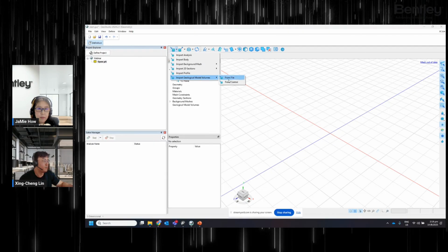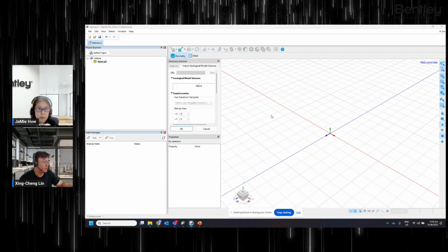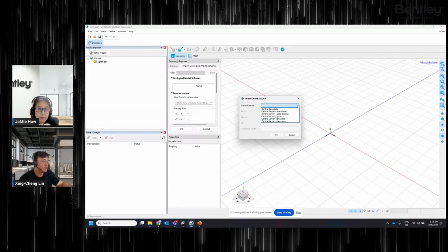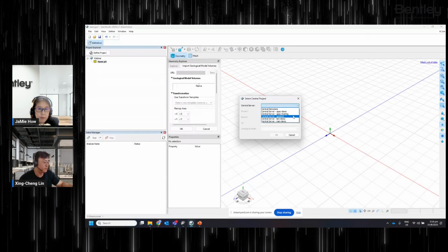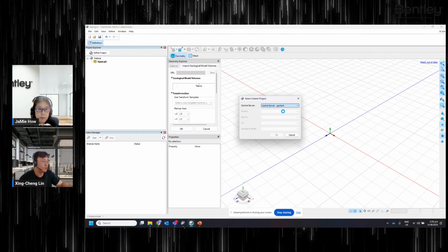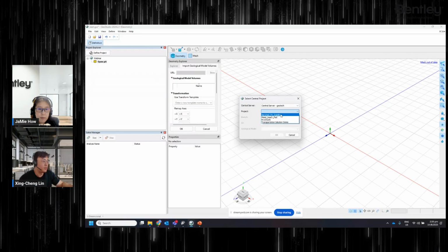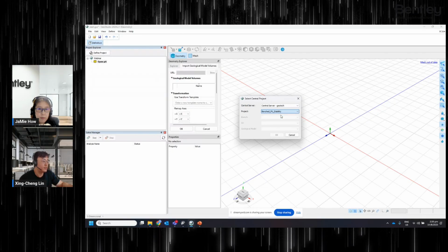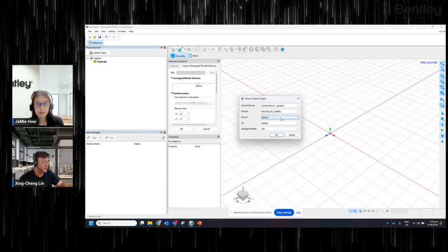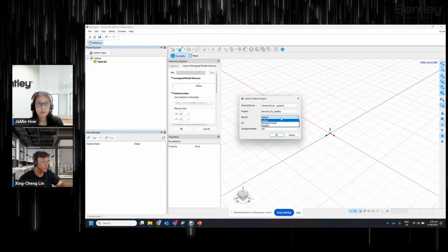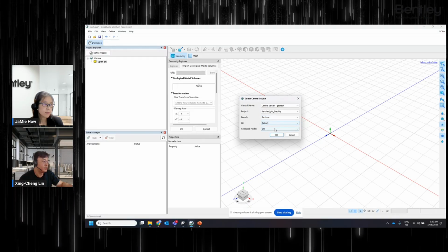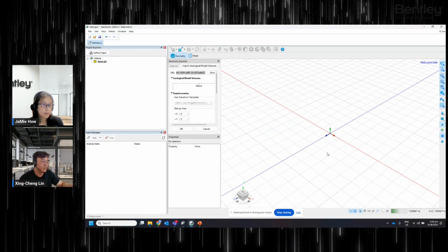In this case, we're going to import from Central. I have already signed in to the Central server, so I'm going to choose the server. It will take a while. I'm going to select this project that's already been published over the Central server, and look at the sections. There you go.